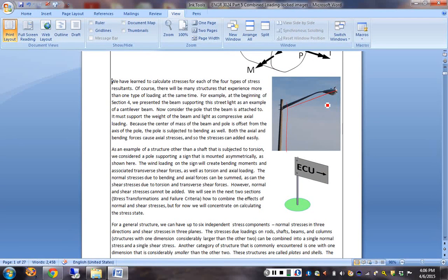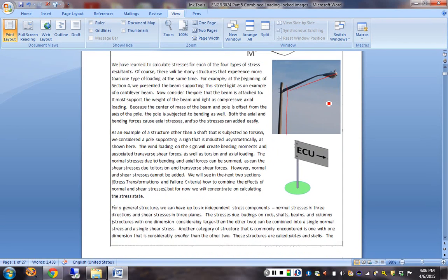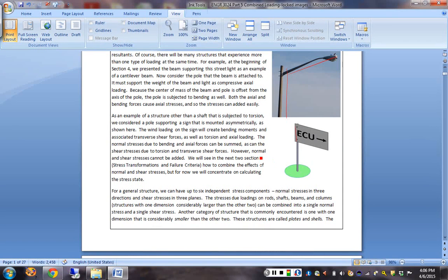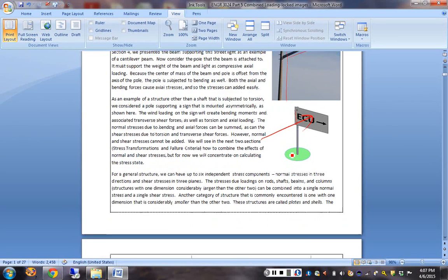If there was some wind load on the light pole, or an easier way to think about that is this sign. If you've got wind blowing on the sign, you've got shear at the connection point where the sign is concreted into the ground. You've got twist on the sign, as well as a bending moment that would tend to make it bend over onto the ground.